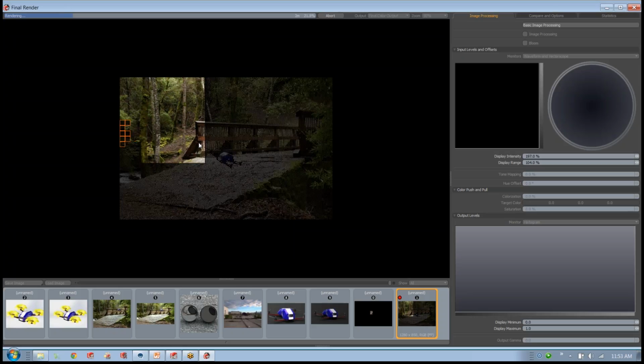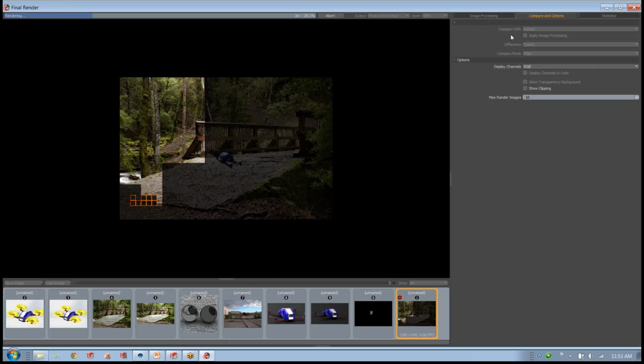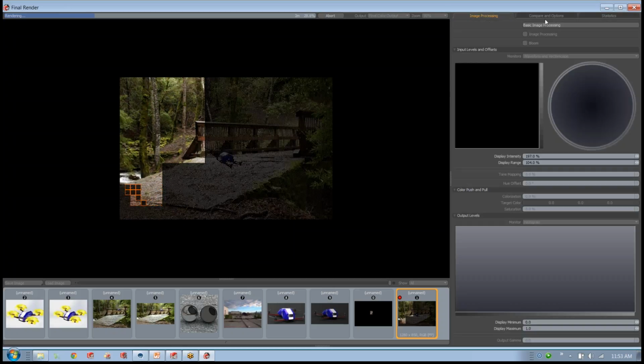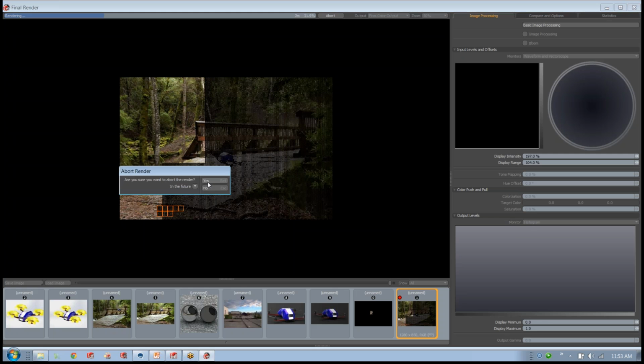Like I mentioned before, the more cores you have available, the quicker the processing is going to go for creating your final rendered image. Now I've already got some images that I've created ahead of time, so we'll go ahead and abort the rendering for now. But one thing to keep in mind, you do have some additional post-processing options for changing colors, lighting filters, etc. If you'd like to explore some of those, you have quite a bit of options to choose from in PhotoView 360.